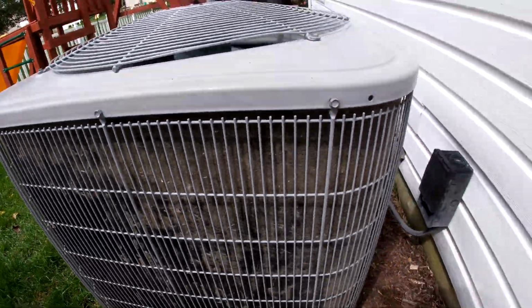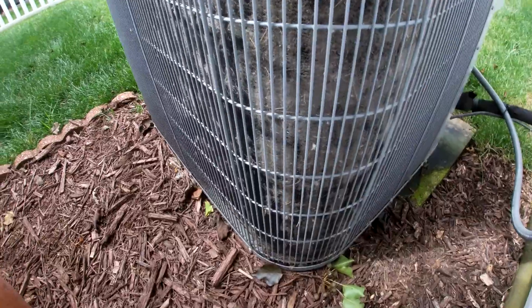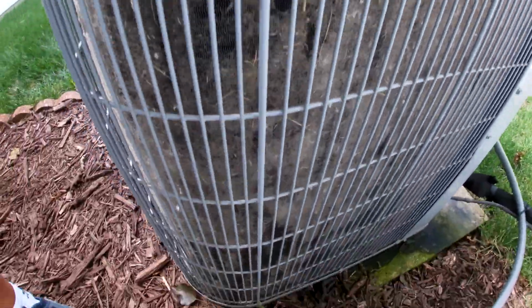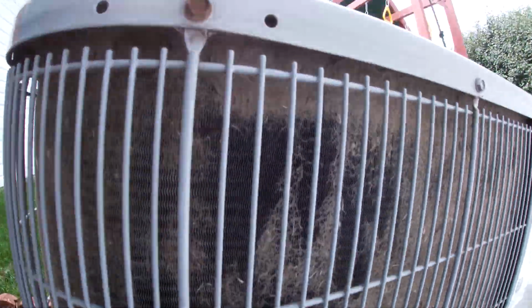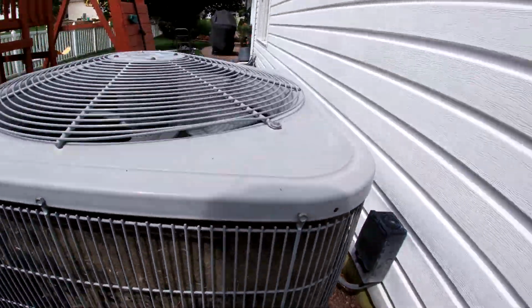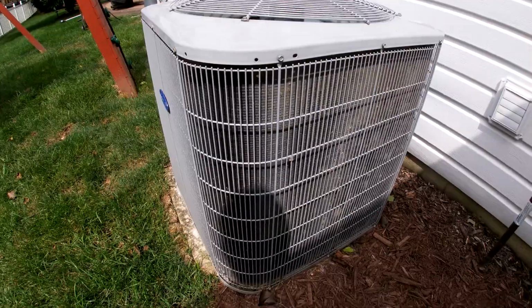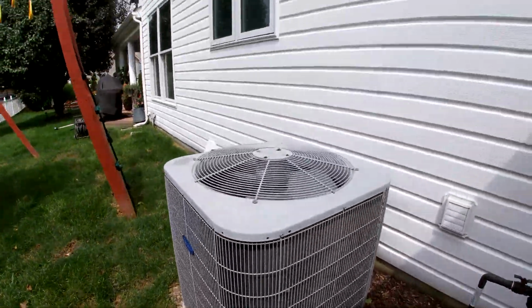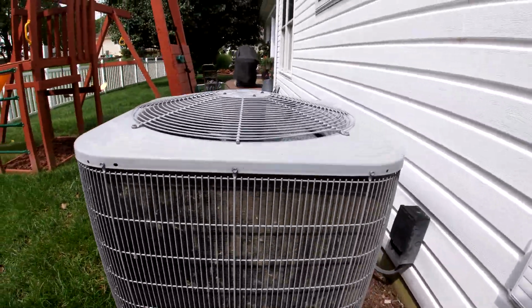It will normally clog in the rear of your air conditioner closest to your house because this is where most of your outside cooling air is pulled through your condenser coil. This degree of clogging will not ruin your air conditioner. However, it will significantly increase your electric bill because your air conditioner has to run longer to dissipate your home's heat energy to the outside surrounding air.